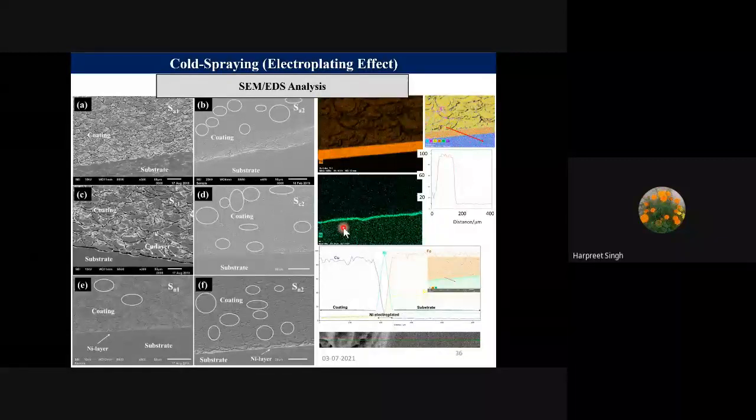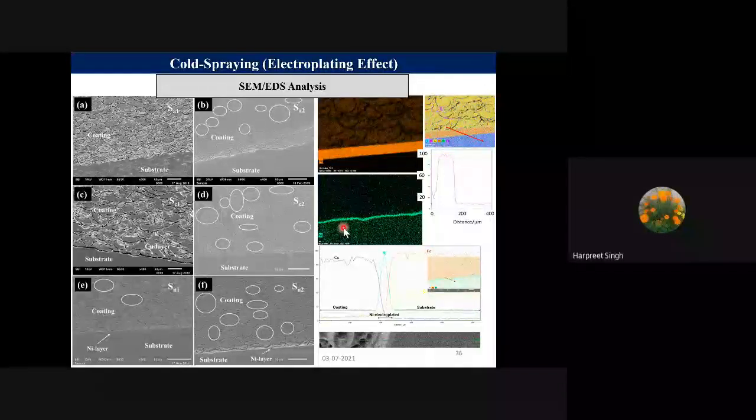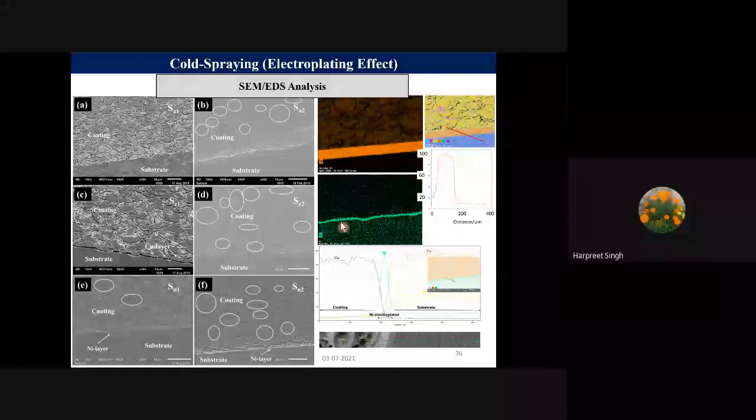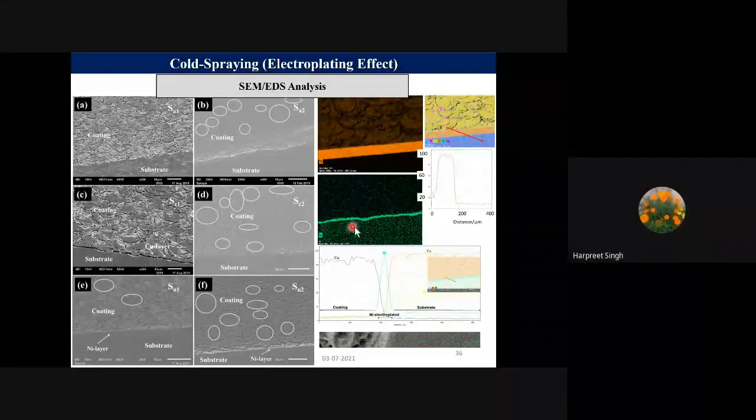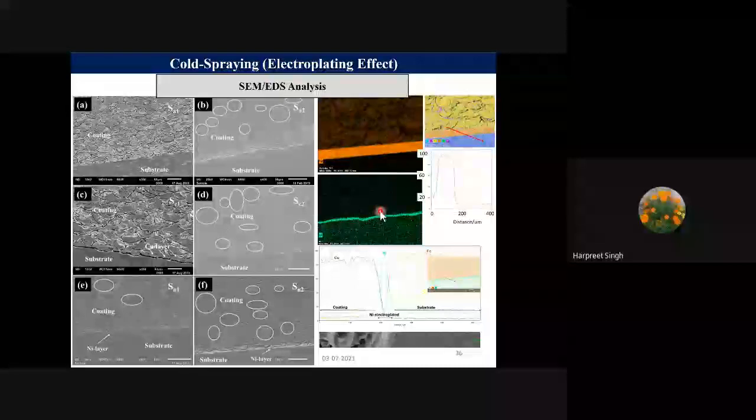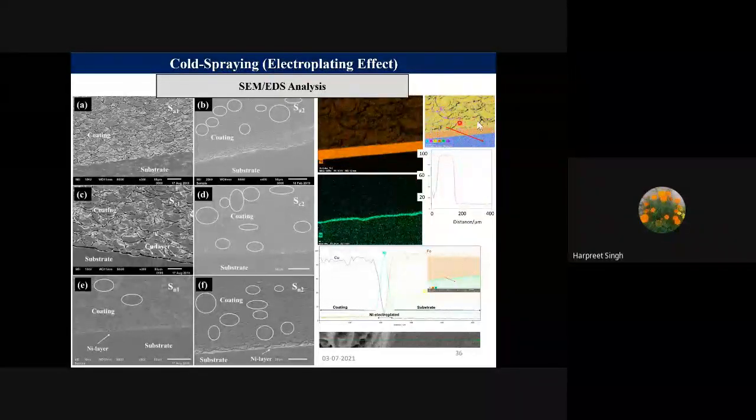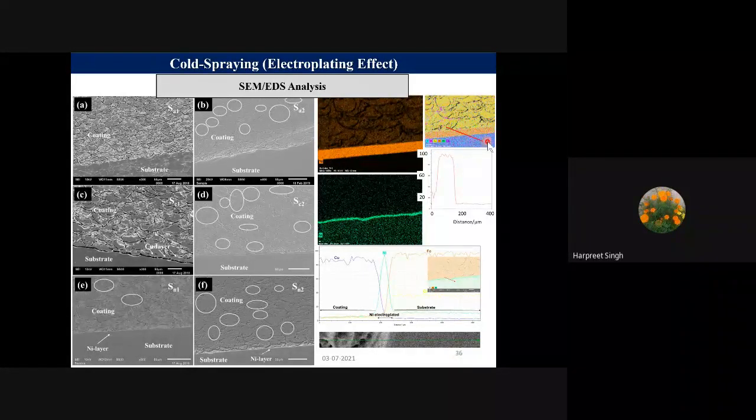Okay, so nickel, chrome, this copper don't have what they call affinity towards steel, for that matter, right? So that's why nickel was introduced in both cases, but here it was a very thin layer, but here it's a very thick layer. This is referring to this third case. I'm sorry, let me clarify this. Okay. These are again combined composition images by EDS. This shows very nicely where the main copper, nickel, and the steel are, and so on. These are the lesions here. You can identify this matter.